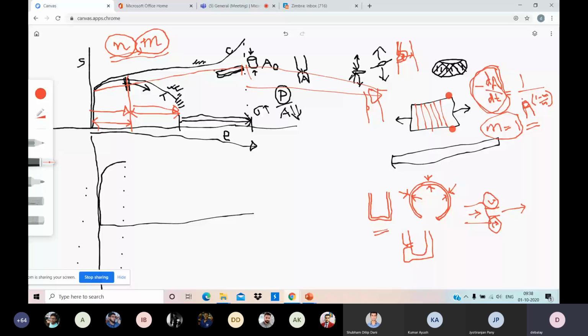I am trying to draw a tension test curve. Okay, now last question, sir. Why is the engineering stress in compression higher than in tension? Of course, area is increasing, load requirement is increasing, but I am drawing load by area. So I am drawing stress. Why is the stress requirement higher in compression when it is deforming under strain hardening? Or afterwards also, why is the stress requirement higher?